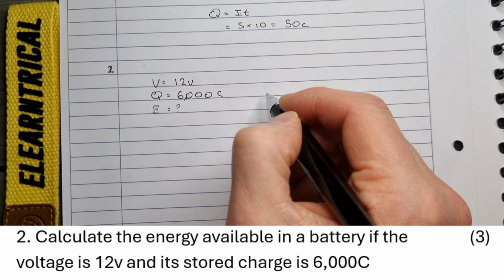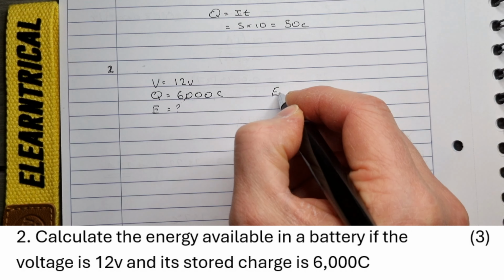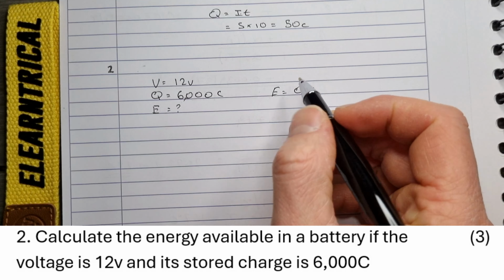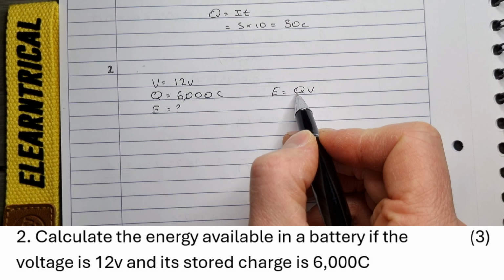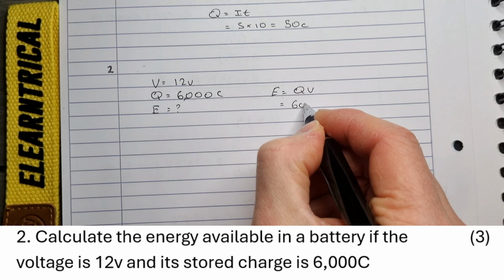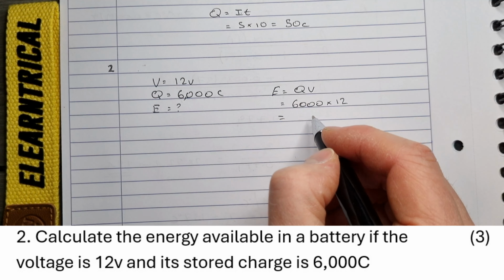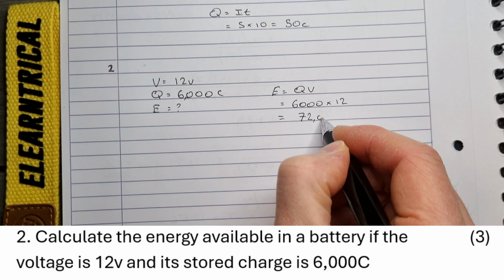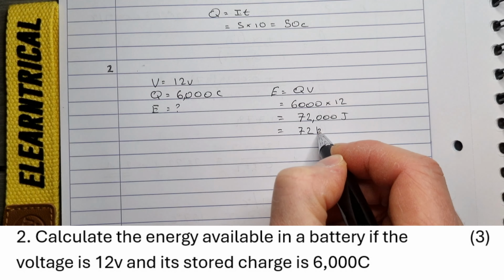Well, E equals QV, or E equals VQ, tells us the amount of energy available based on the voltage and the amount of charge in there. So we can take our charge of 6,000 coulombs and multiply it by our voltage of 12, and that gives us 72,000 joules, or 72 kilojoules.